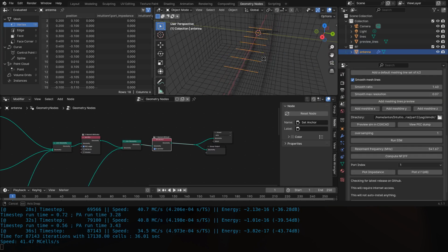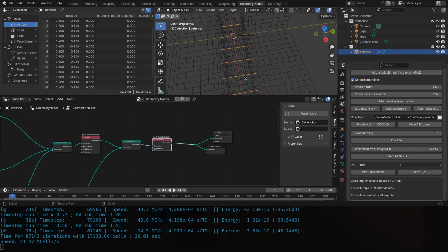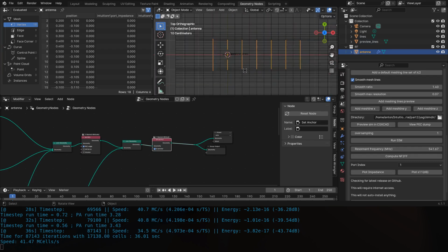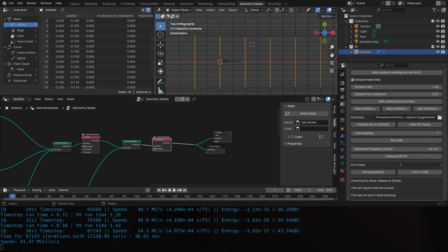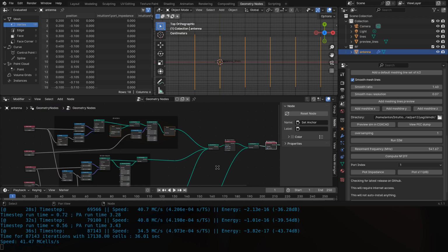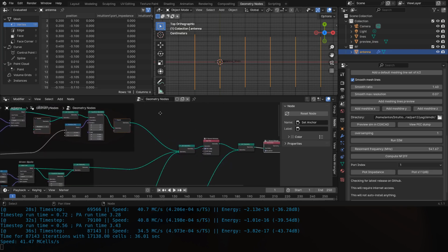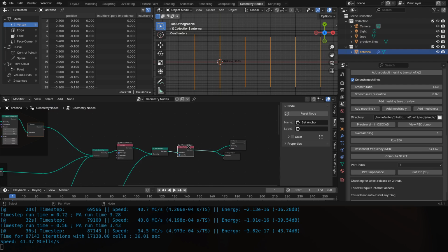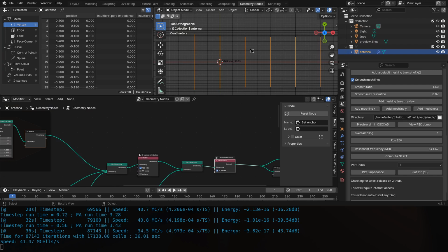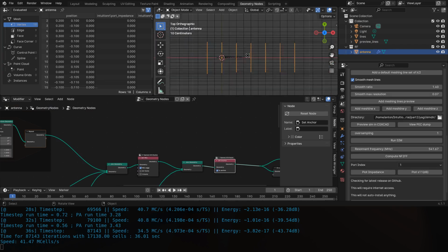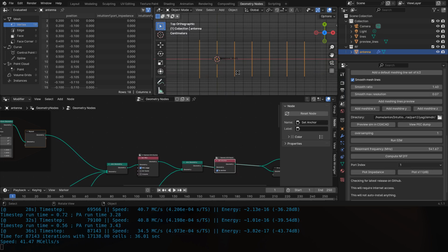Okay, now what we can do if we want is improve the meshing quality. As you can see, I have only meshing lines on the elements themselves, but usually near the perfect electrical conductor's edges you want to have some more finely defined mesh. So we can do that within the geometry nodes group, and what we can do is add some geometries that will be set in the output, but not define it as a conductor and just define it as an anchor. And what this will do is add the lines without changing the primitive in the simulation.